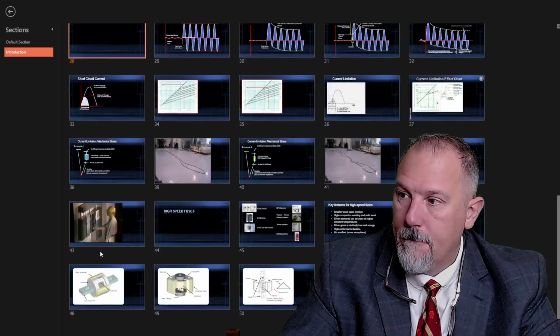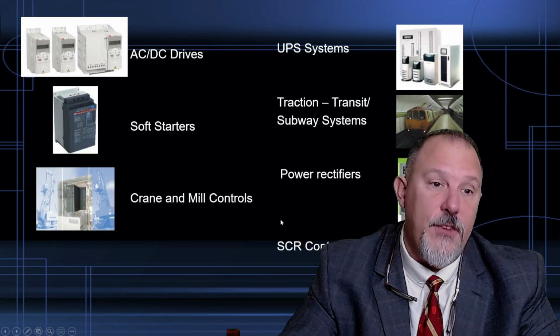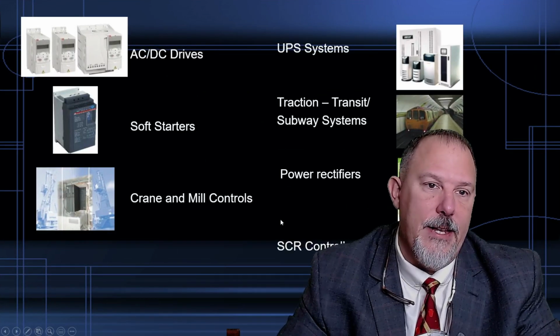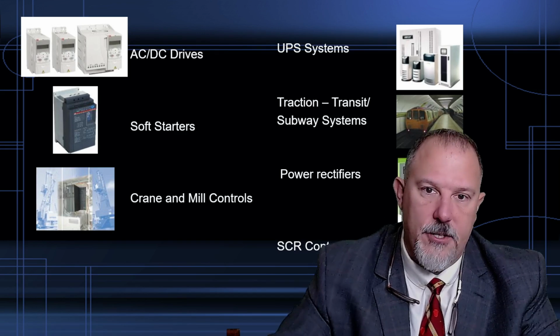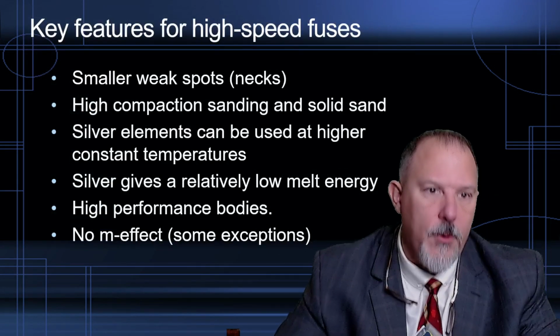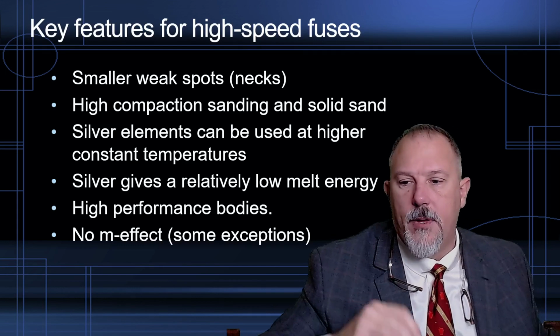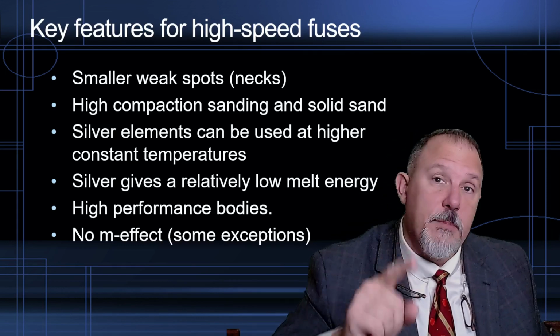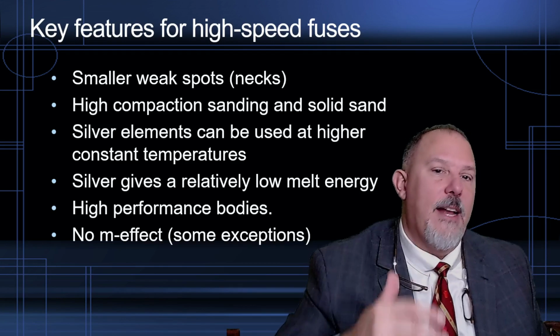We already talked about current limitation. And I will mention quickly and briefly, there are high-speed fuses that are used in drive applications and things of that nature. They have smaller weak points. You don't size a high-speed fuse based upon an ampere rating. You size a high-speed fuse based upon the amount of energy that you will let through.